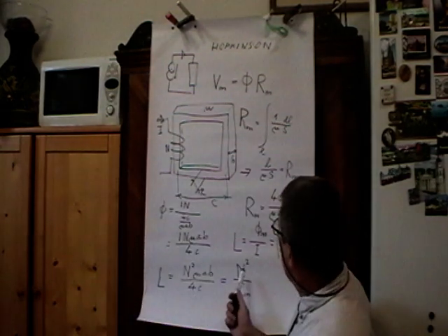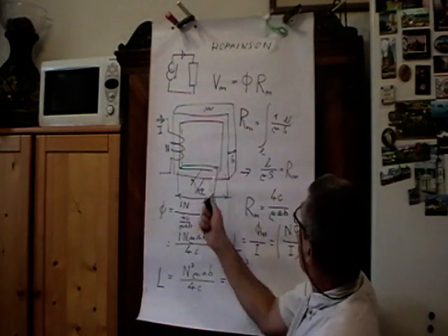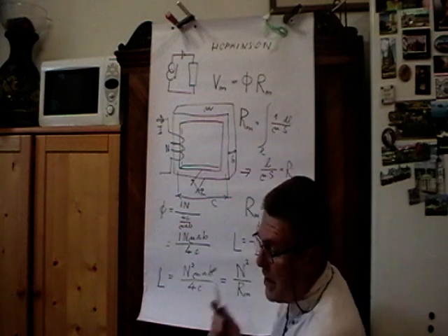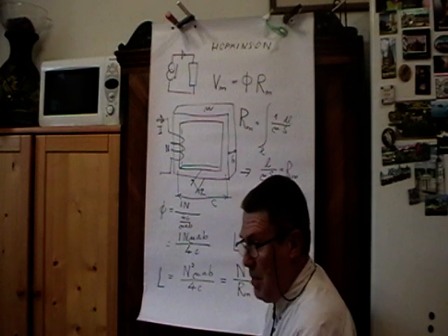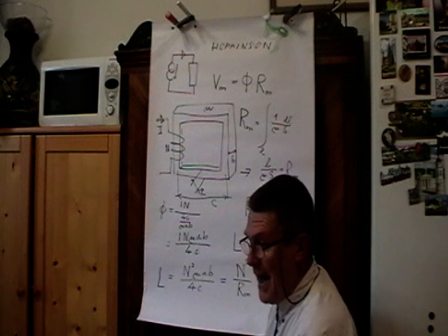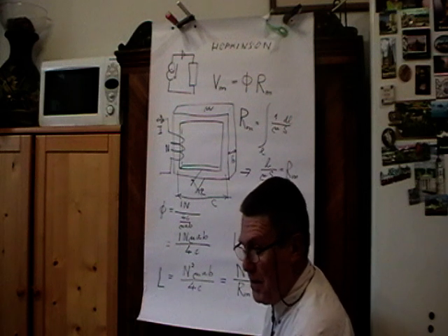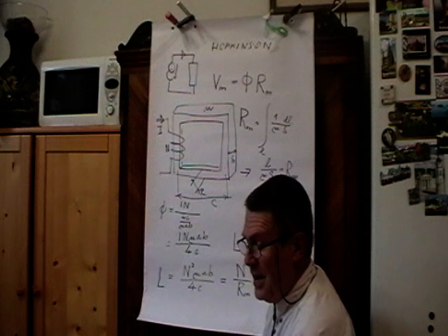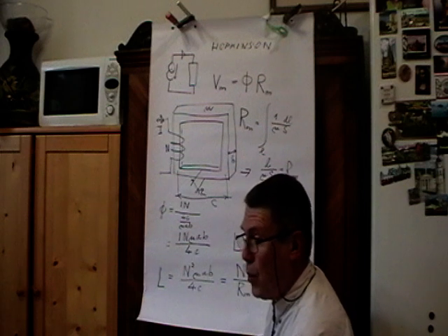We could obtain it by just manipulating symbolically with the equations. But this is an important result that says to us that once we double the number of turns, we will get 4 times the original inductance. So the inductance depends on the number of turns quadratically.